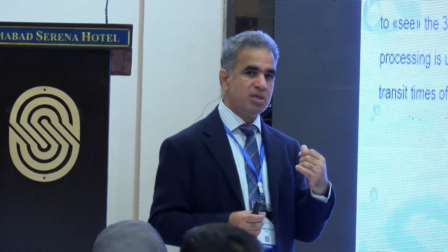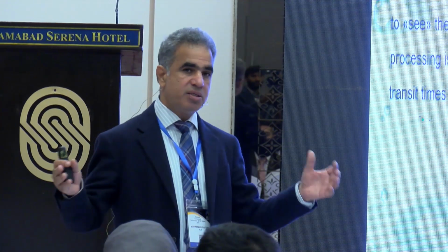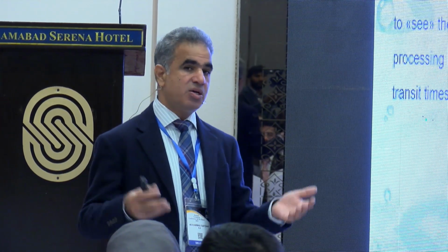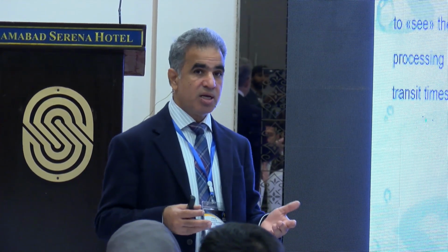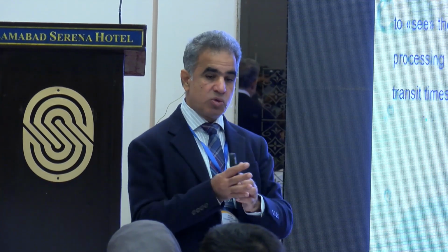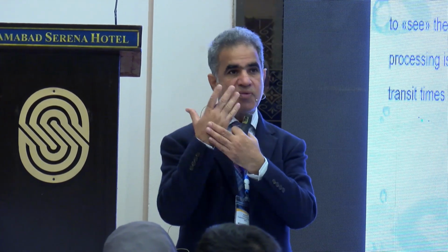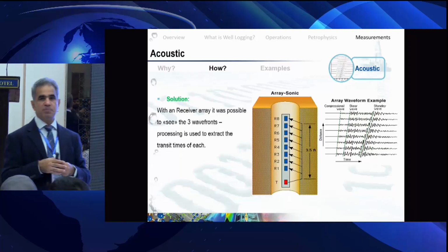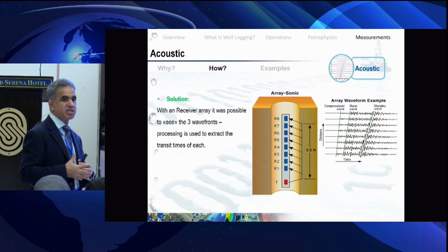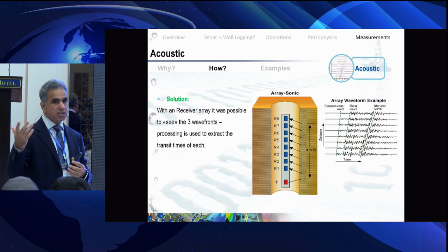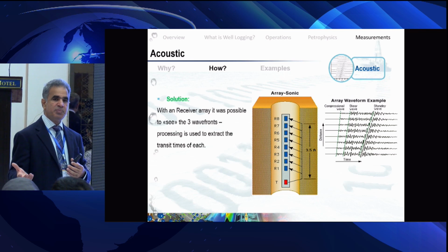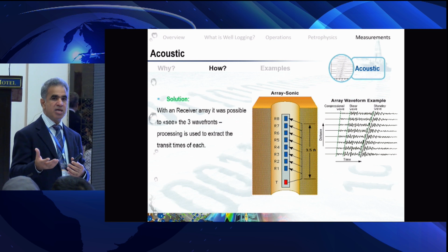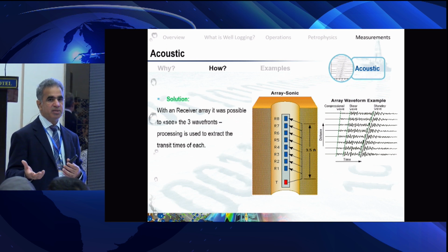If the borehole is large, it will affect density, it will affect neutron, and it can affect sonic. But pad tools, the tools which need to touch the borehole wall, are more affected by bad hole. Tools which are not pad tools are least affected by the borehole. This is just certain physics and tool-based design.